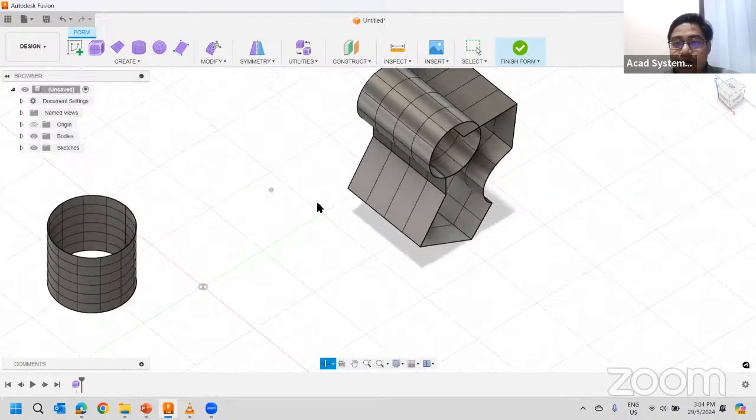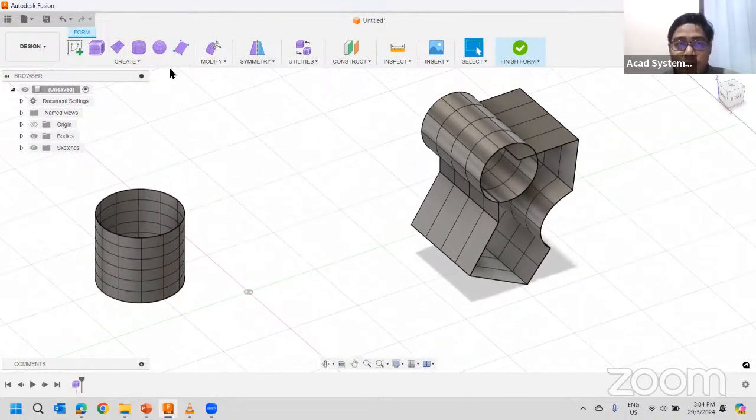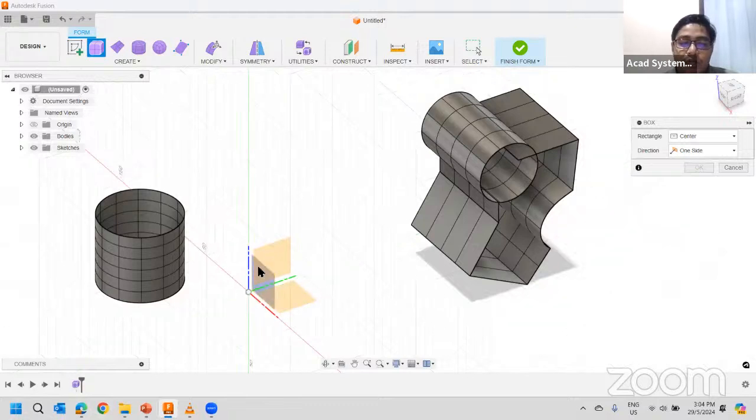So just a little bit of a reminder: when you use forms, anything that you add or change and modify will not be recorded inside of the history down here. This one is only to click for overall settings, overall changes that you make from here. So anything that you add, maybe I add another box from here, it will not be recorded, and I cannot go back and change the size. So I need to do it manually. So just a bit of a reminder for me.